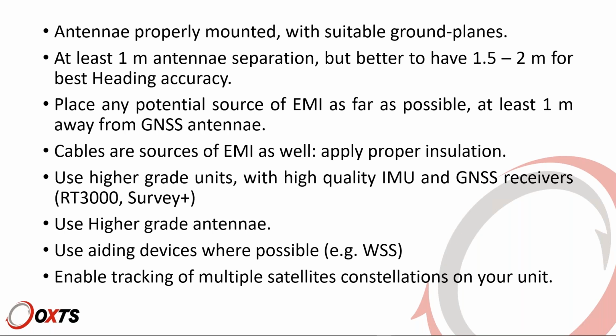Use higher grade antenna, better at reception, and often they will have embedded protection from multipath. If possible, use aiding devices such as wheel speed sensor. More on this in a bit.